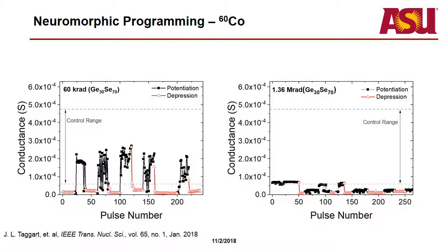But you're actually controlling the current as you're doing this, so you can limit the filament growth during a DC sweep. But for pulse testing, you're essentially only giving a small window of time to allow that silver to migrate to the filament. And so these tests are a little more sensitive to the ion migration, because it's not going to sit there and hold the pulse until it gets enough silver. It'll cut off once you get to, in this case, 10 microseconds. And so any silver that hasn't made it to the filament isn't going to make it, and the filament's going to partially dissolve.